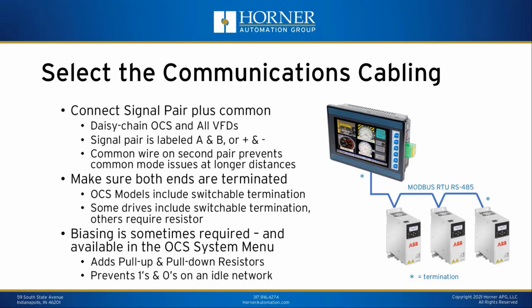So in the case of the XL7 that we're showing there, that and some other similar models, I should say, have dip switches for setting termination, whereas some of our other models have a bit that you can set from the system menu or from your application program that turns on and off the RS-485 termination. So you need to make sure that both ends are terminated.